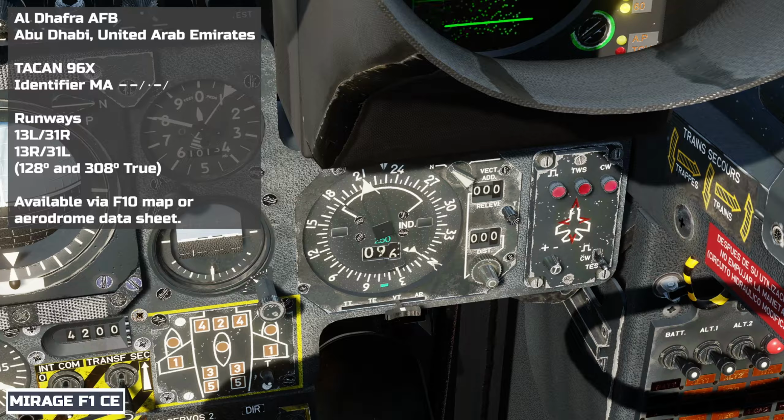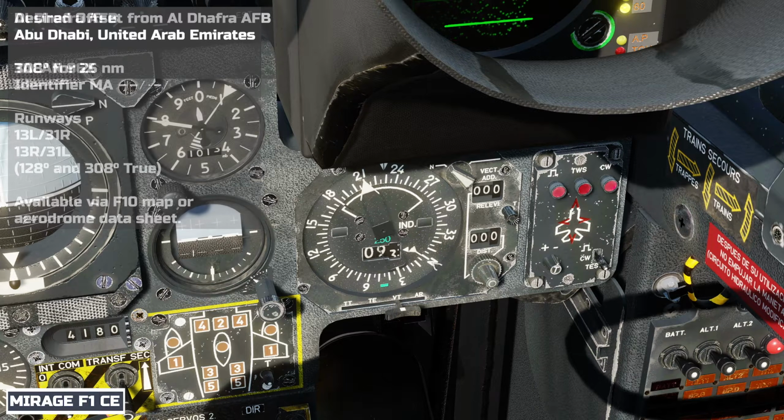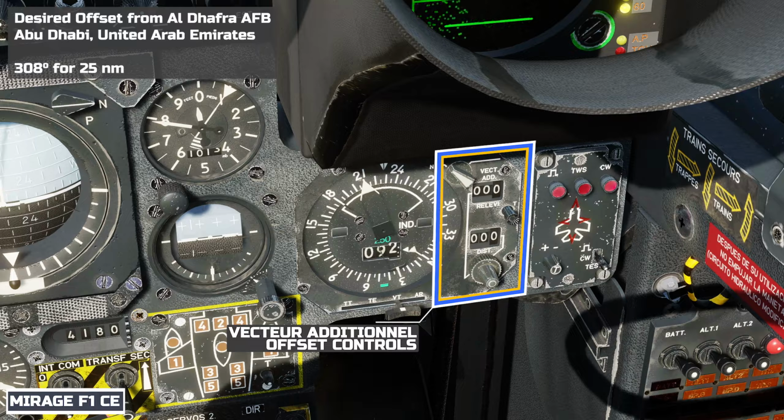As the true heading of the runway is 128 degrees, we want to offset its position by the reciprocal, which is 308 degrees. We also want our offset to be a sufficient distance for us to get set up for our landing. Let's give ourselves plenty of time, so we will set the offset to be 25 nautical miles from Al Dhafra. The offset is set using these controls here on the right side of the IDN.